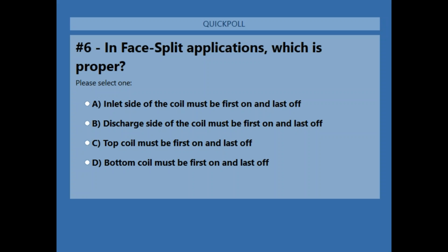Well, liquid lift, excessive liquid lift will reduce capacity because the horsepower of the compressor is used up trying to push the liquid uphill. It will increase the temperature of the compressor. That's a possibility because we're using a lot of horsepower and not pumping the refrigerant around like we should. So you lose capacity. The main result is you lose capacity because the horsepower is used up trying to get that liquid uphill. So that's probably easiest to leave it at that.